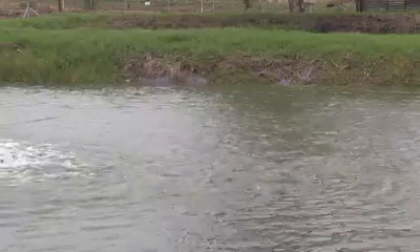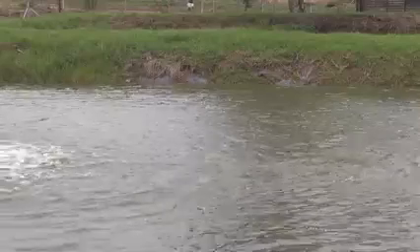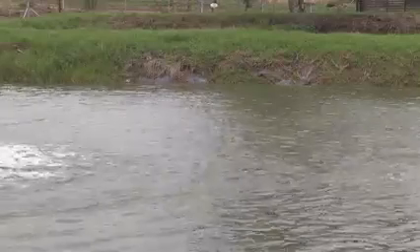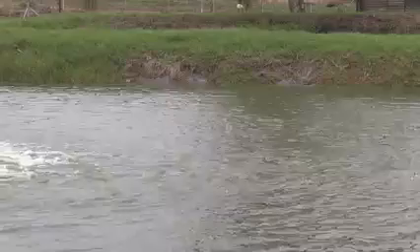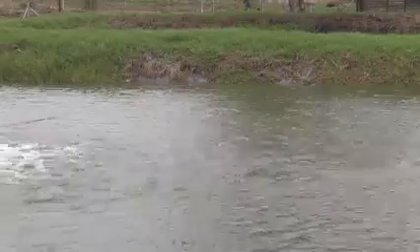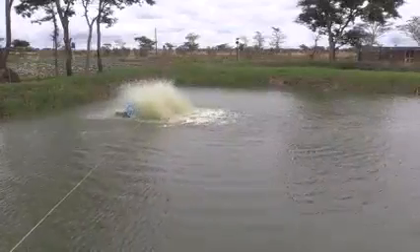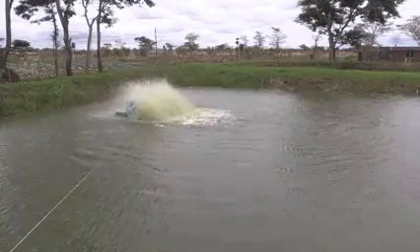After you construct your pond, make sure your pond has a drainage where you should be able to drain. It should be able to drain automatically in case it rains and you are not there to control the water level. So you need to put a drainage pipe on the deepest part of the pond. That's where you put your drainage. After you do that, you then start preparation to stock.